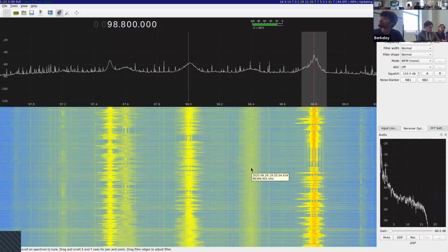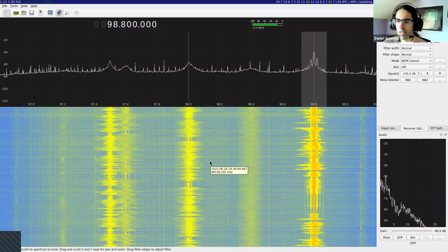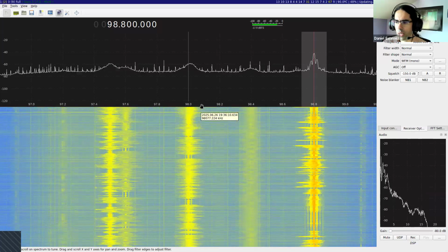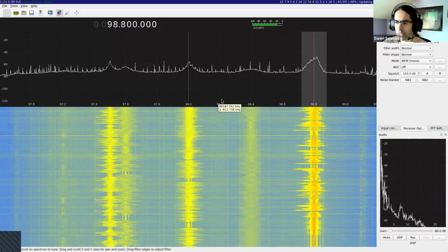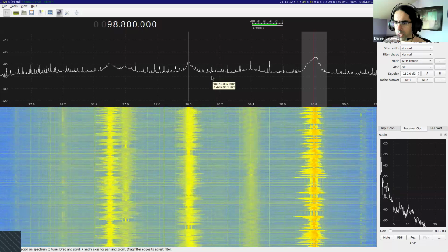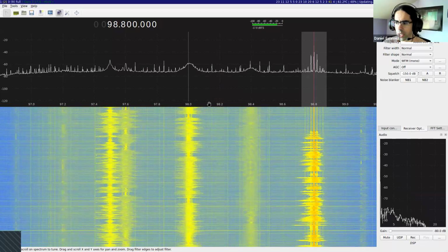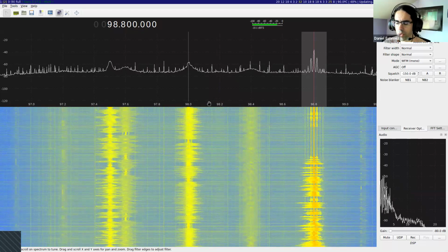You got a lot of little spikes across the spectrum there, Daniel. Why is that? Oh yeah, that's a good point. So I have pointed at the FM stations on the spectrum. Everything else on the spectrum is interference. I'm next to a computer. I have the RTL-SDR next to a computer screen.